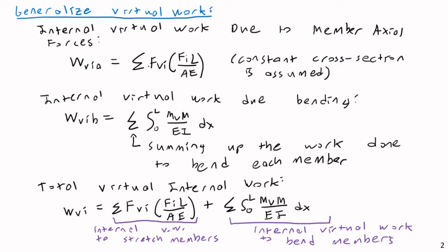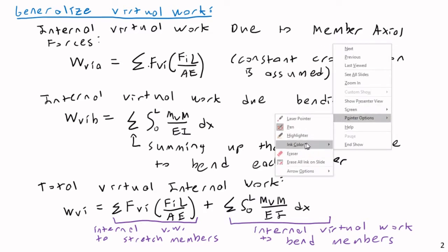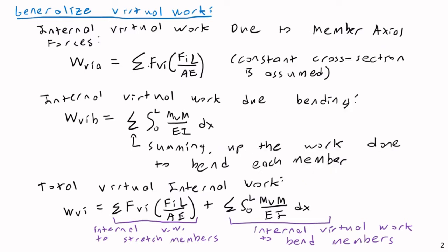So now we can see that working with frames really isn't so difficult. All we're doing is combining together the previous expressions we already used for both trusses and beams. But let me put this into a final form. I want to recombine this with the external virtual work forms to produce our final equations for frames. So final total virtual work expressions.